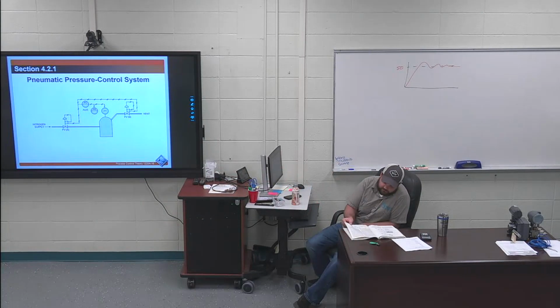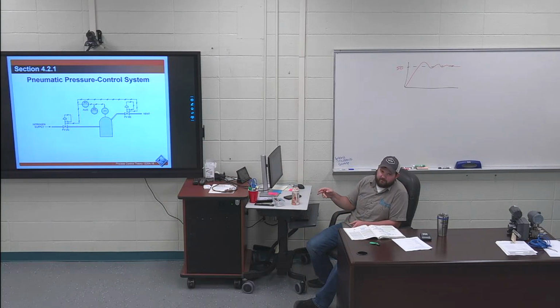Moving on to page 50. Still with the electronic pressure control loops, the first sentences on page 50 are highlighted. In this control application, the supply valve typically fails shut on loss of signal and the vent valve fails open. This prevents overpressurization of the tank. So make sure the way the valves fail, you have them related to either the electronic pressure control loop or the pneumatic pressure control loop. Know how the valves fail.